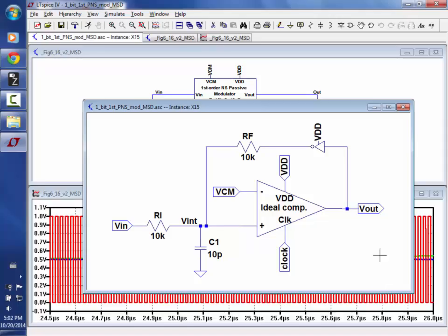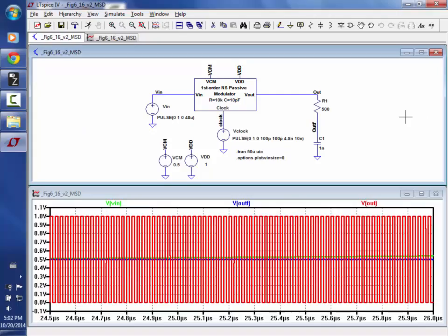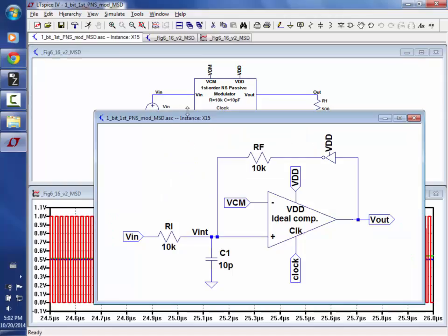Okay, so what I want to do is go back, or actually we can just show this here. We'll use an analog integrator, and we'll look at figure 6.31, which is the equivalent of what we're looking at right now. Okay, so wait, let me back up. Does everybody understand that this voltage wiggles? So if I move Vin towards 500 and this voltage is too low, it'll move up, and the amount of charge that I get through here will vary because of that variation.